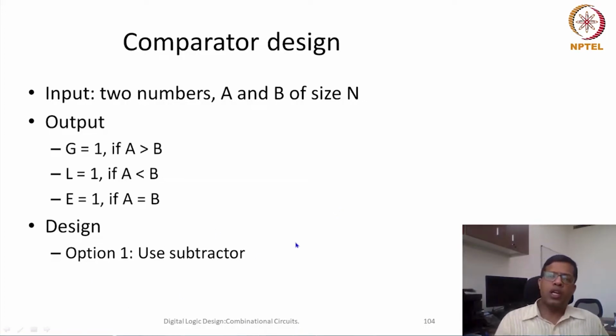If in the circuit where we are using the comparator there is already an adder that could be reused, then people use this type of comparator, because we can share that adder and reutilize it for other purposes. For example, in our computer systems or a processor, only one of addition, subtraction or comparison would take place at a time. In that case, it is very common that we use this type of comparator.